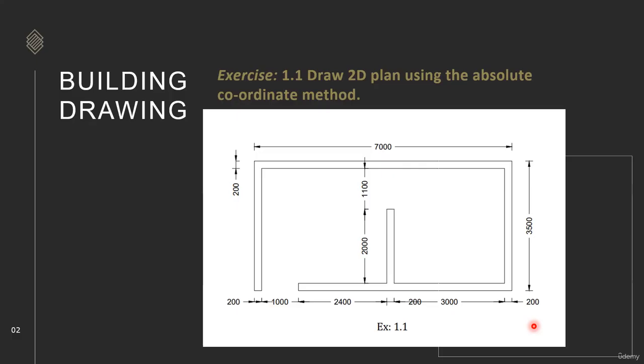So nowadays load bearing structures are very rare. In most cases it is outdated. No one is going to construct load bearing structures. For small structures we go with the load bearing structure, and it is economical, and also where the usage of the structure is very less, in those cases also we go with the load bearing structure. The construction method is also very easy in the load bearing structure, and the materials consumed are also very less, so it is economical. So we use those load bearing structures.